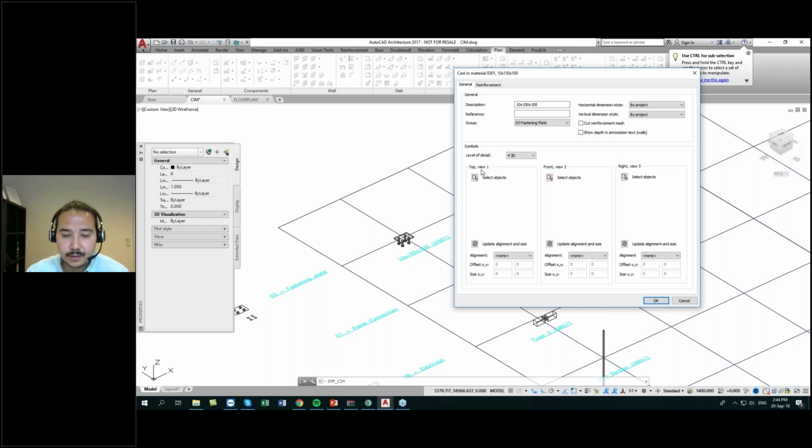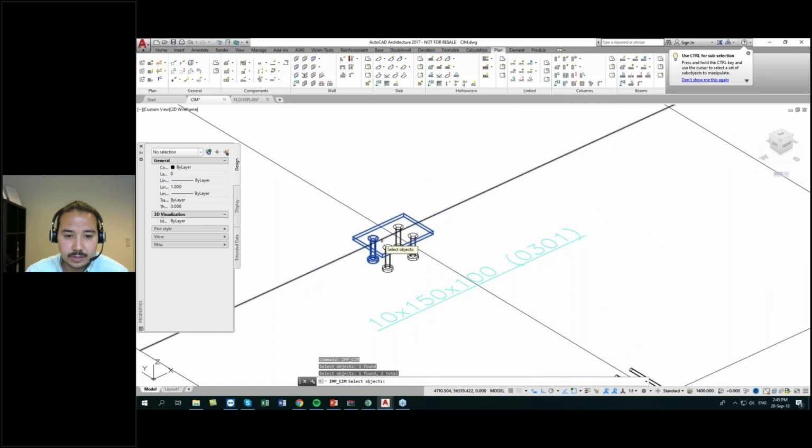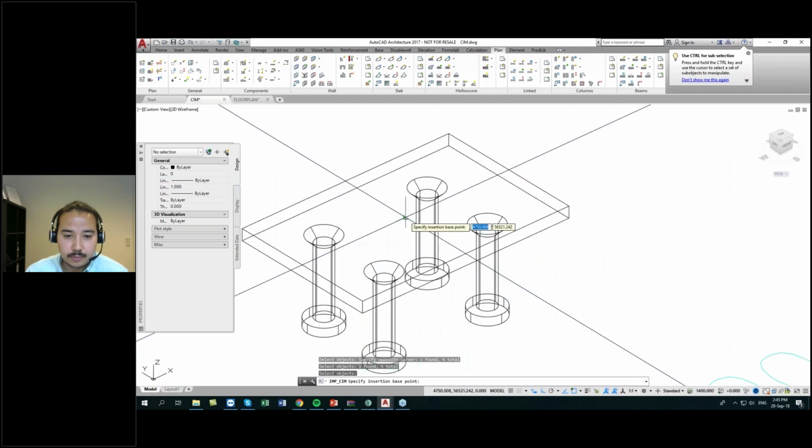I always choose 3D. I go in and select my top view, select the components that should be part of the custom material, press enter, and select my insertion point, and that's pretty easy to find because I have these lines here. Then it's going to ask if I want to create view 2 and 3 from this view. I will just say yes to this because I want the other views also. And if I want to create a 2D level of detail for the views, yes. And where I want to put the 2D level of detail, I want to put that on fine.